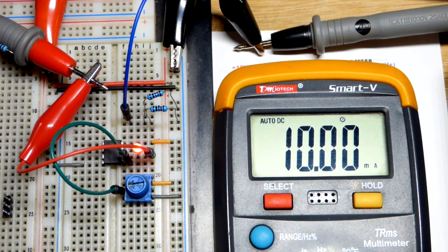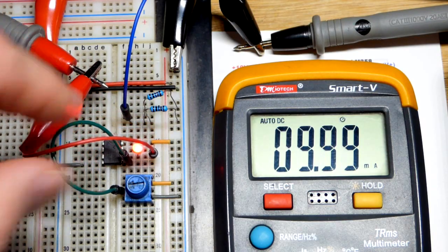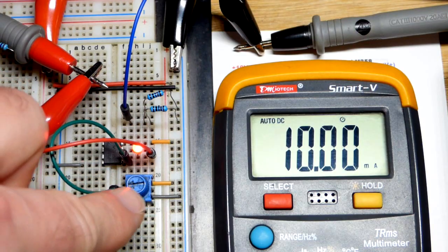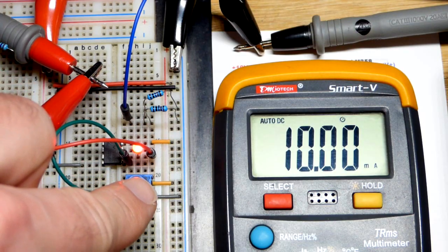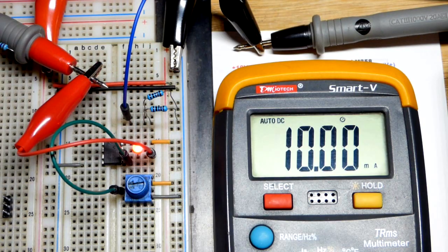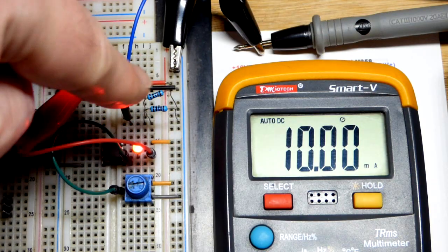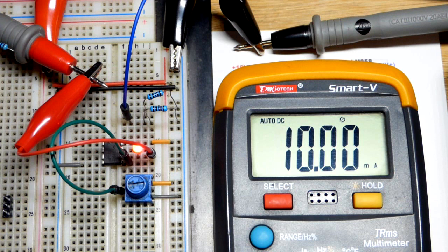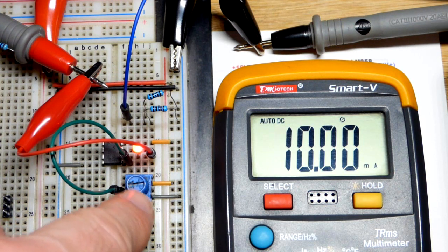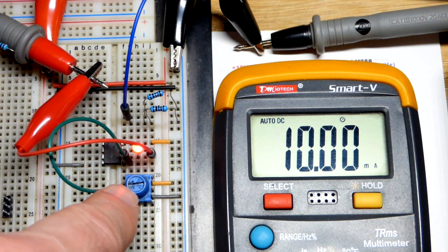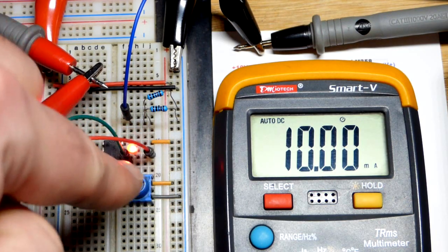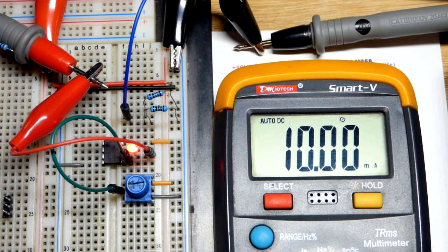So for a current source like this, if you have a certain amount of voltage set, but you want twice as much current, then you can just put the same amount of resistance in parallel. That's one of your options there if they're fixed resistors. You could also use a variable resistor to make it variable as well. This could be wired as a variable resistor instead. You could just have the wiper going to ground, get rid of that positive one, not for where it is now, but you could use that up there. But in any case, we're going to move on.